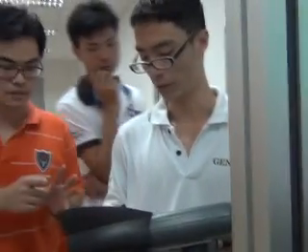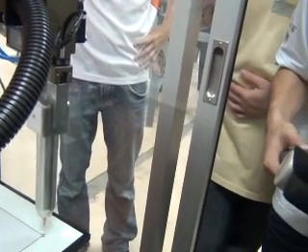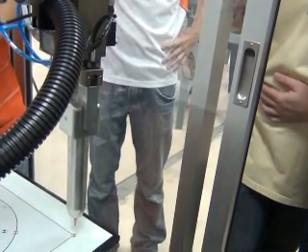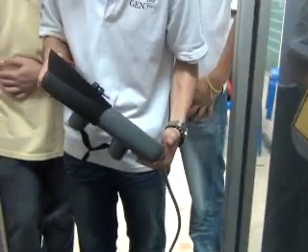Now you're using which coordinate system? The global coordinate. So the global coordinate is actually almost the same as this. So the x positive is this, y positive, and z positive. And the ABC is just the reverse of x, y, z. A is for z, and B is for y, and C is for x. Yeah. And when you're teaching a robot, always make it